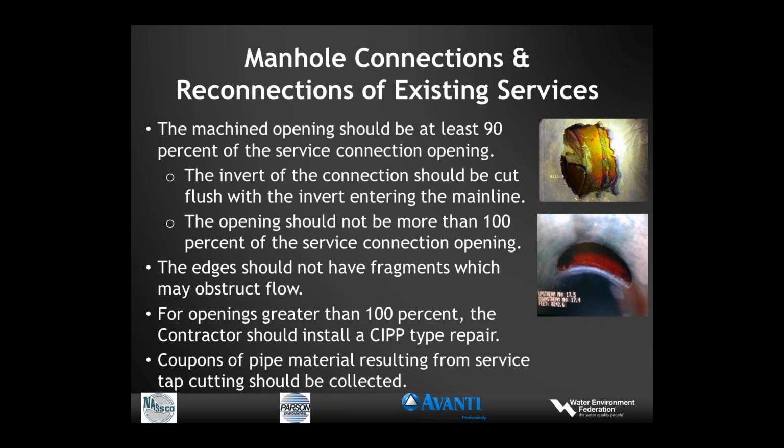The upper photograph you see is a very poor service lateral cut. You know, it's irregular, it's got jagged edges. It's also not flush at the bottom with the lateral line, thus this is a plug waiting to happen. The cut at the bottom is a good service lateral cut. The opening should not be more than 100% of the service connection opening.